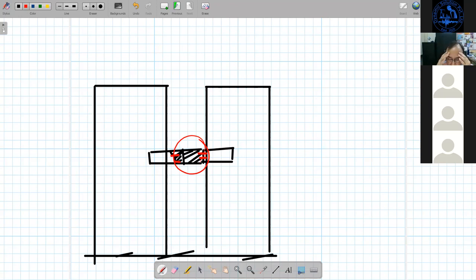Okay, so Suraj Gurung asks a simple question: is it okay to connect the slab with the lift wall, or make it separate at floors? No, it should be connected, because if you are constructing the lift well as a shear wall, it will provide a lot of stiffness and strength to the building. And if you have not connected it with your building, then you are not taking advantage of that shear wall. So it should be connected.